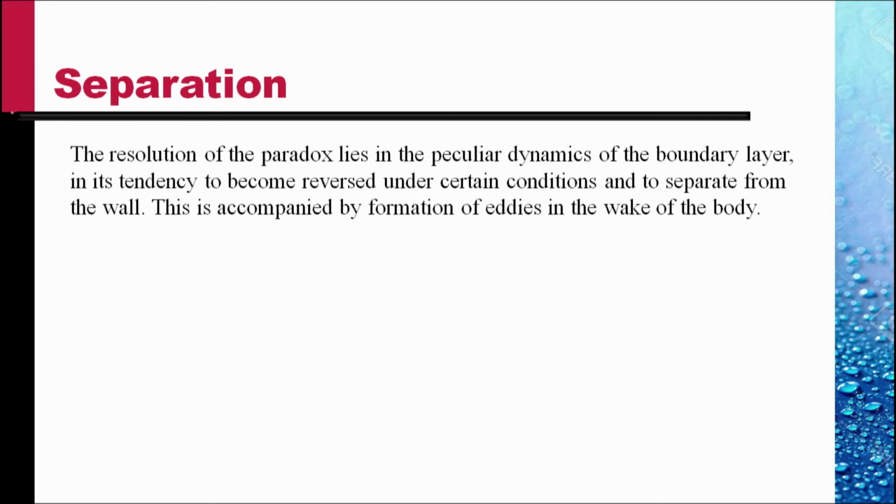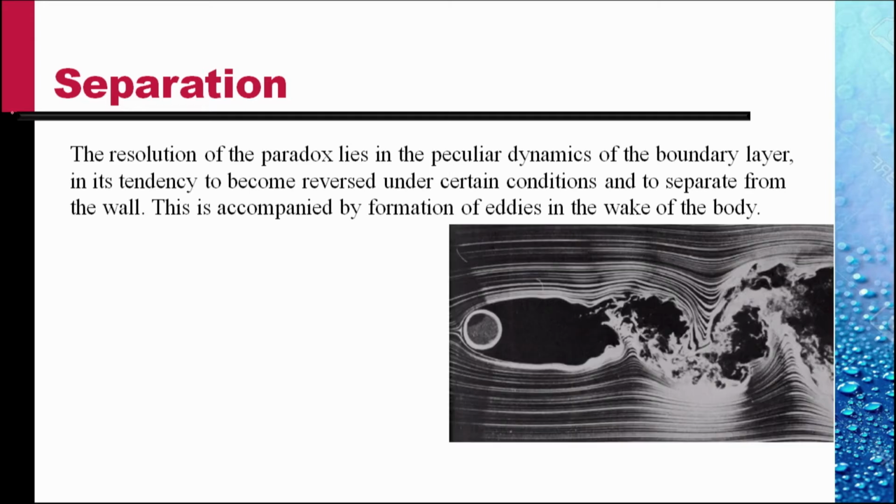The resolution of this paradox lies in the peculiar dynamics of the boundary layer. That is, in its tendency to become reversed under certain conditions and to separate from the wall. This is accompanied by formation of eddies in the wake of the body. We have seen that flow behind a cylinder looks like this.